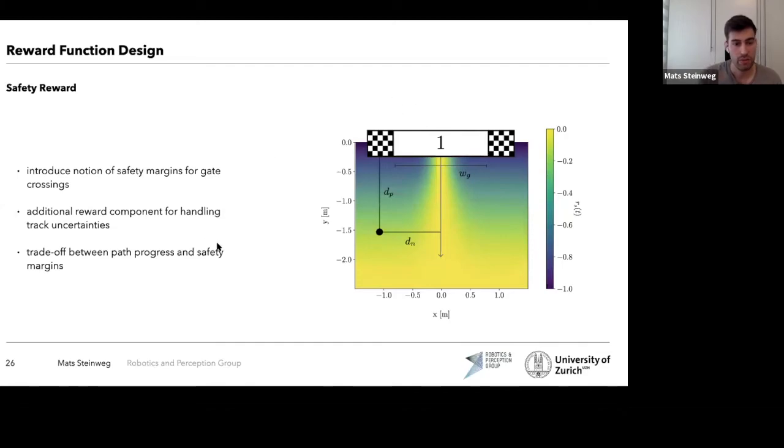Then we see what type of optimization method is CPC. CPC is not really a specific optimization-based method. It's an approach for generating time optimal trajectories by optimizing the shape of the trajectory jointly with the allocation of the traversals of individual gates to time. So in the end, it's just a formulation of a nonlinear optimization problem. I think that as a high-level summary, that's okay.